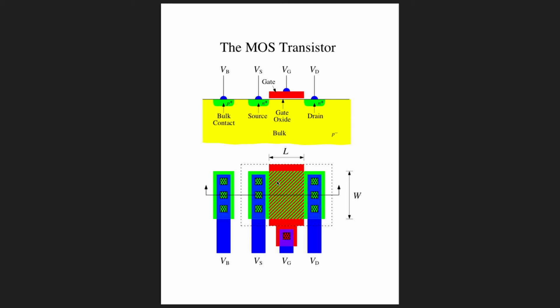One other thing I will mention about the MOSFET, contrasted with the bipolar transistor that we have been talking about, is that you'll notice that the device here is physically symmetric with respect to the source and the drain terminals. With the collector, there was an asymmetry in the structure, and that had to do with the doping level. The emitter was very heavily doped.